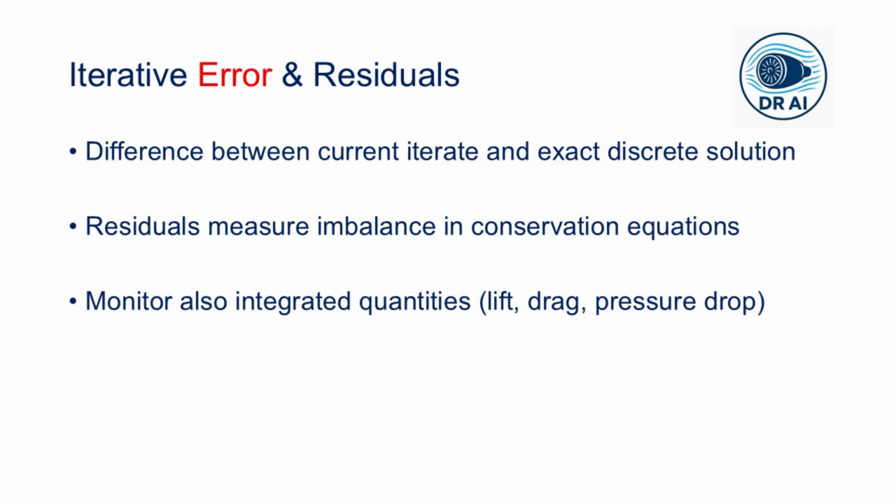But residuals alone can lie. They may plateau due to round off or poor conditioning. Always monitor an integrated quantity like lift, drag, pressure drop, etc. So if that quantity stops changing while residuals are still high, you might be fine. Conversely, low residuals but drifting forces indicate a problem.